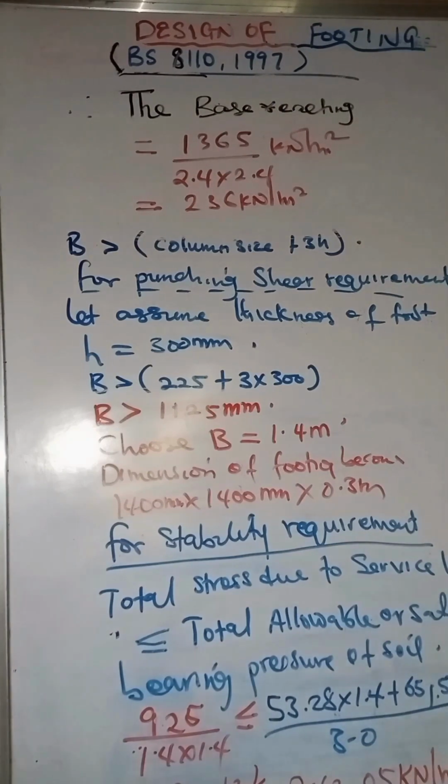Now this pressure is going to be acting uniformly over the surface of the footing. All right. Now in designing the footing, we're going to design it as a two-way slab, like you can see from the board. We'll just pick a strip of 1 meter from this footing and design it as a beam. Okay. So it's going to be treated as a cantilever slab.